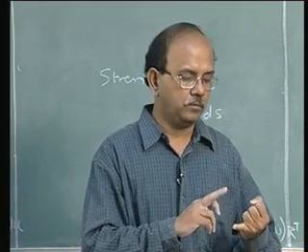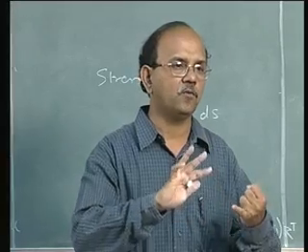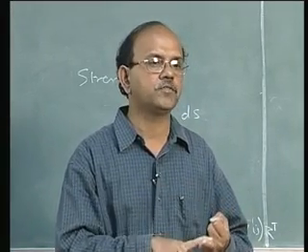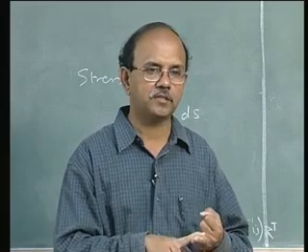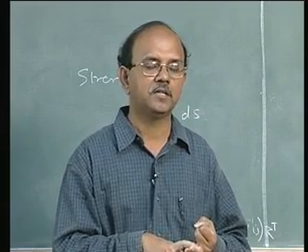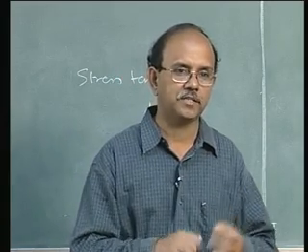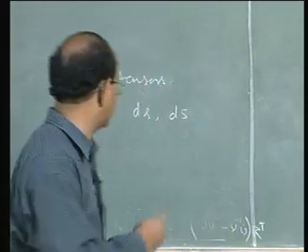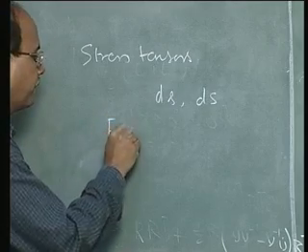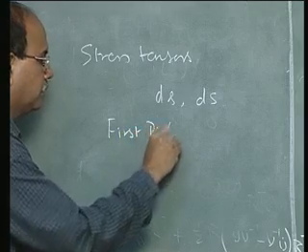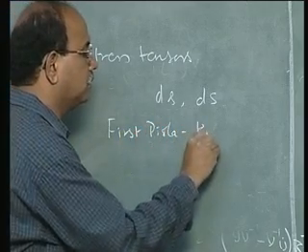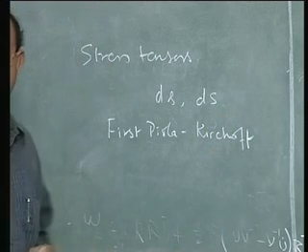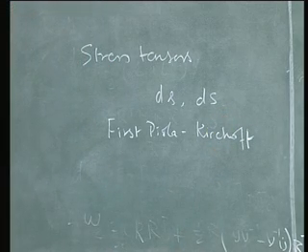So, number one, we have Cauchy stress well defined. We have an equivalent stress measure for the nominal stress. That is the second definition of stress, and I call that in the multi-axial case the first Piola-Kirchhoff stress. First Piola-Kirchhoff stress.